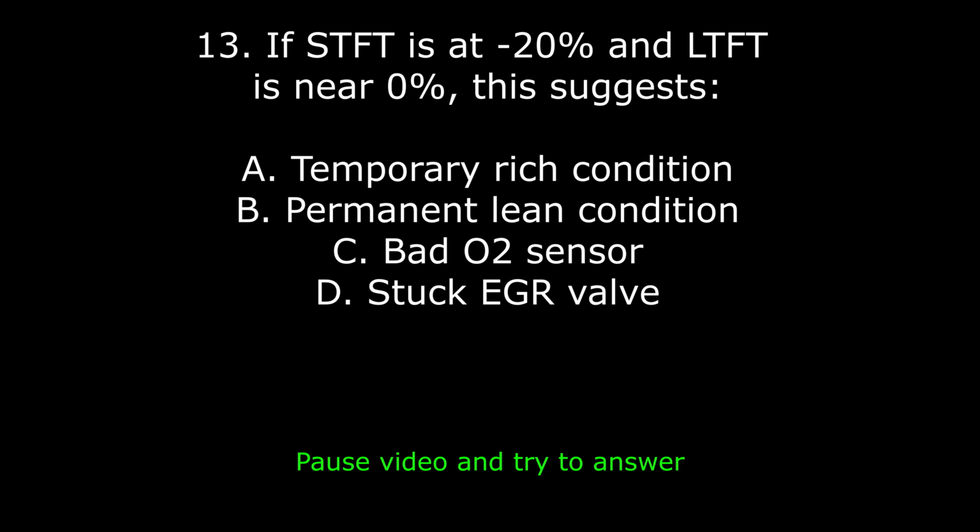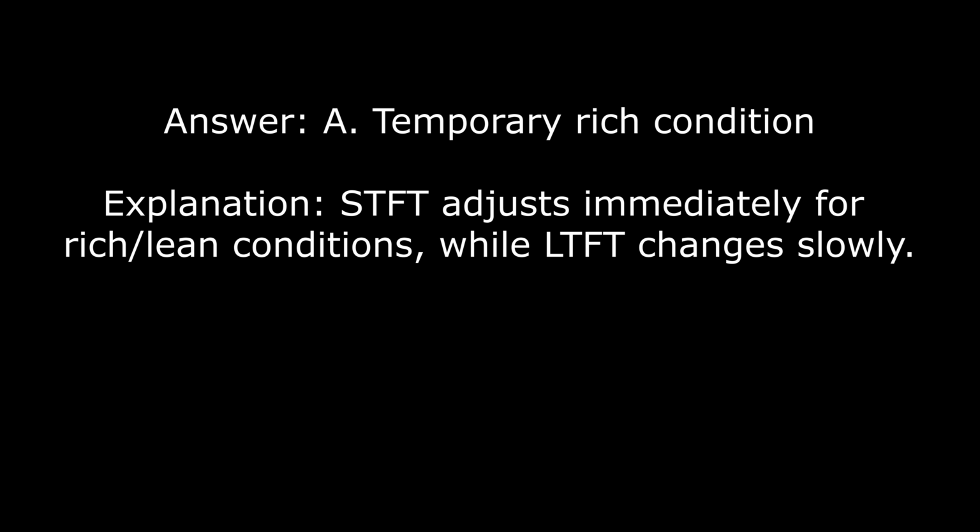13. If STFT is at -20% and LTFT is near 0%, this suggests A. Temporary rich condition, B. Permanent lean condition, C. Bad O2 sensor, D. Stuck EGR valve. Answer: A. Temporary rich condition. Explanation: STFT adjusts immediately for rich or lean conditions, while LTFT changes slowly.